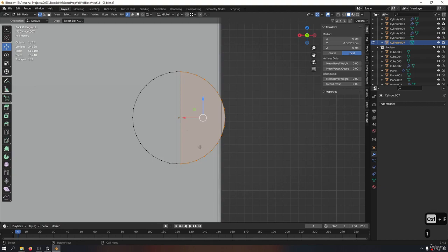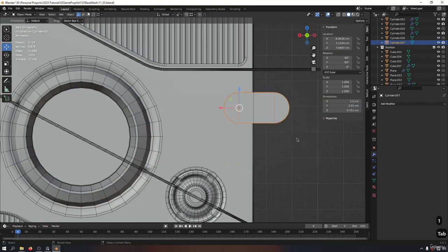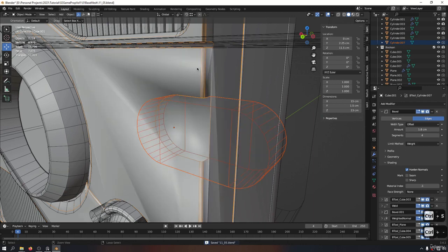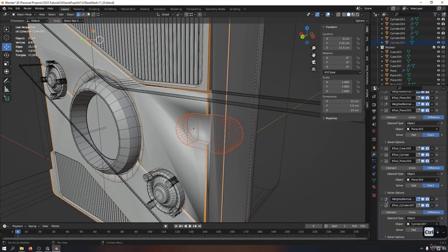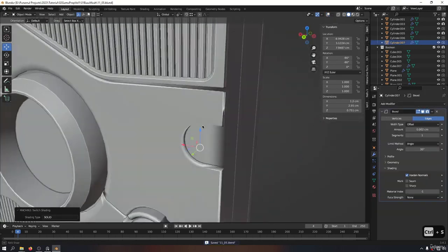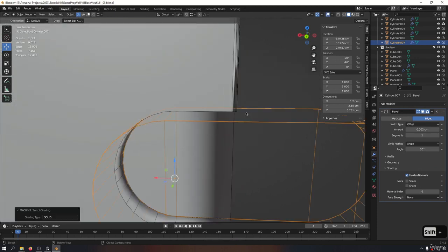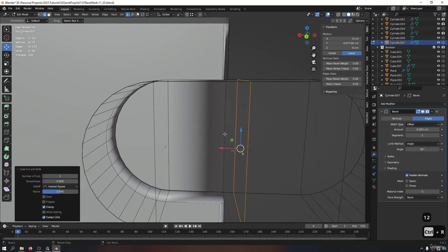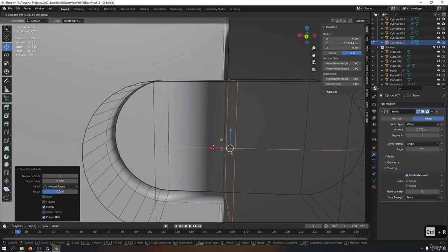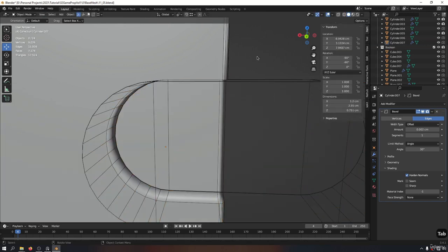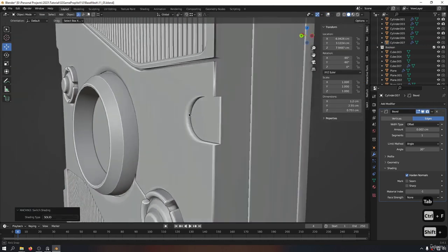I'm gonna take this and drag it out. Okay. Now right away, I'm going to take this one, this Control minus. So let's go bring the weighted normal modifier down the list to recalculate the normals. So it looks like there are some shading issues in here, so no problem. I can go take this one and let's add an edge loop, excuse me, and bring it to here. Okay, move it so that it could change the shading a bit with it.